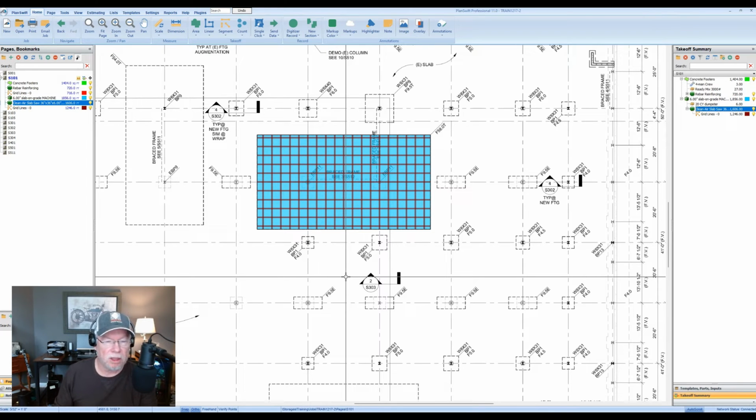And what's the difference between an assembly and a template? It's pretty easy. If I design something and reuse it, for example, this concrete takeoff for the 6-inch slab, and I save it to my templates folder, that's a template. It does one thing. It measures and creates volume of concrete that's going to come out. The other things I add to it, like the automatic calculation of dumpsters and a secondary takeoff for the cutting, that turns it into an assembly.